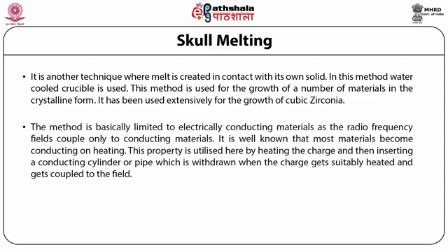The method is basically limited to electrically conducting materials, as the radio frequency fields couple only to conducting materials. It is well known that most materials become conducting on heating. This property is utilized here by heating the charge and then inserting a conducting cylinder or pipe, which is withdrawn when the charge gets suitably heated and gets coupled to the field.